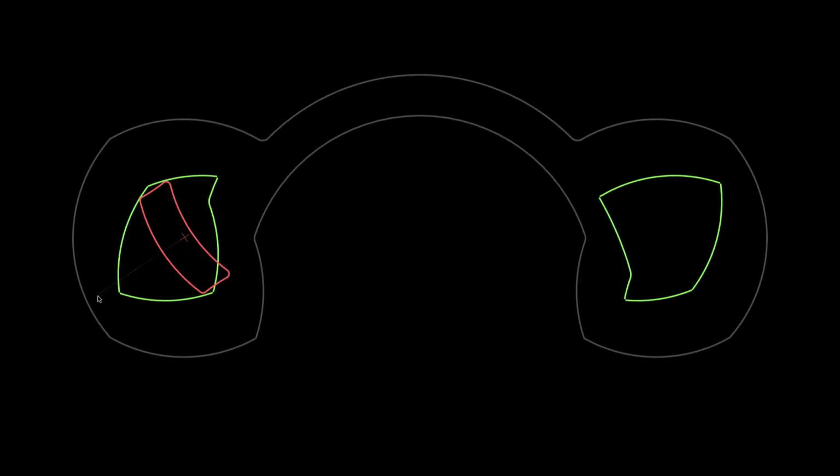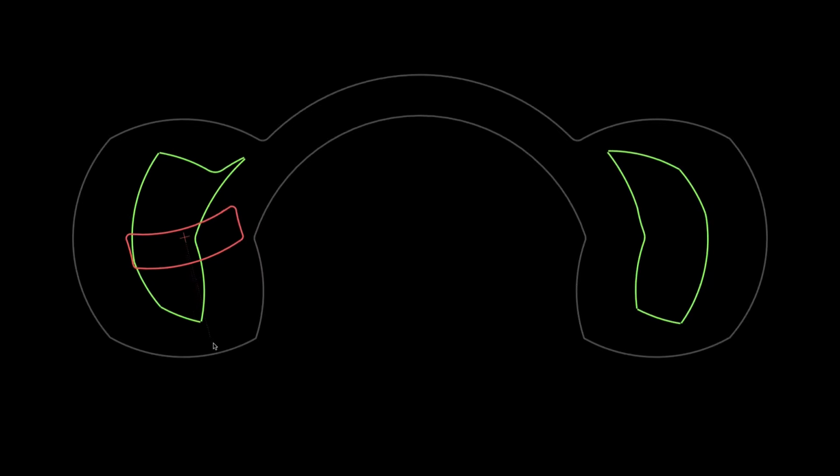The contributing edges from the robot and obstacle can be checked by translating the robot along the free space boundary. Notice how the robot remains inside the obstacle so long as it is not moved outside the subedges. The subedges illustrate the cross-sectional boundary of the free space for the robot's current rotation, theta.